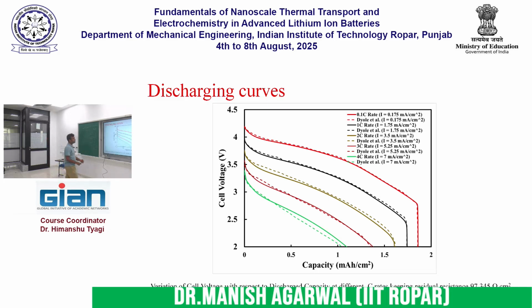The red one is when I am discharging the battery at a really slow rate, 0.1 C, and the last one is when I am discharging at the 4 C rate. Theoretically the battery capacity is roughly here, but when I discharge fast, the actual capacity becomes only 50% of the battery.